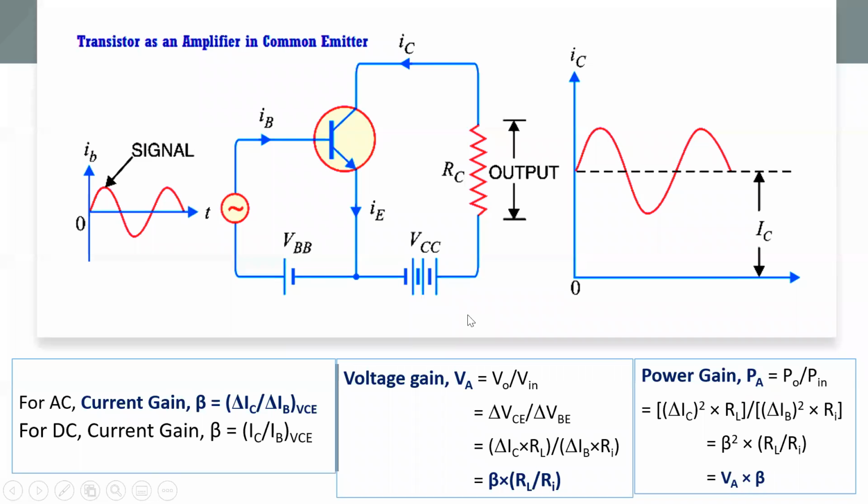Is that clear how to draw the circuit? Yes. So these are the points to be noted. The emitter base junction should be forward biased and the emitter current direction should be such that emitter current is equal to base current plus collector current. So emitter current enters this junction, base and collector current leave the junction. And we put the polarity of the cells accordingly, positive to negative. This is how the current flows.